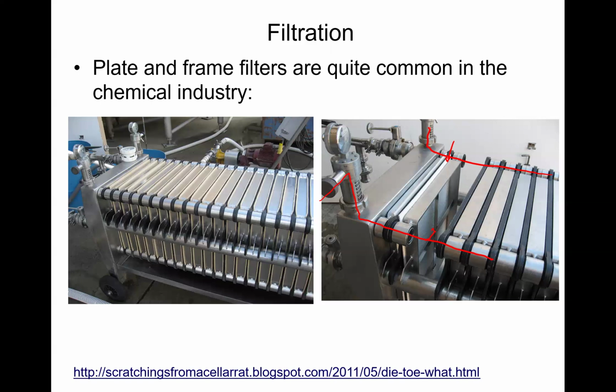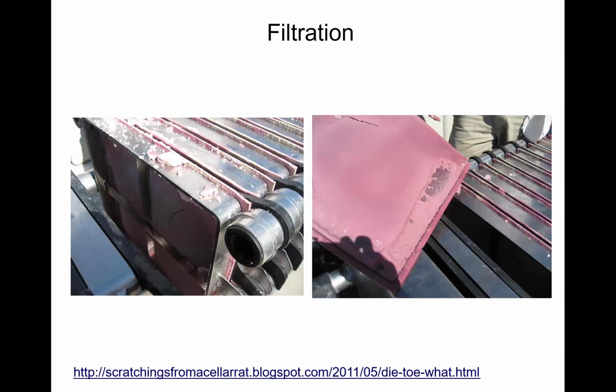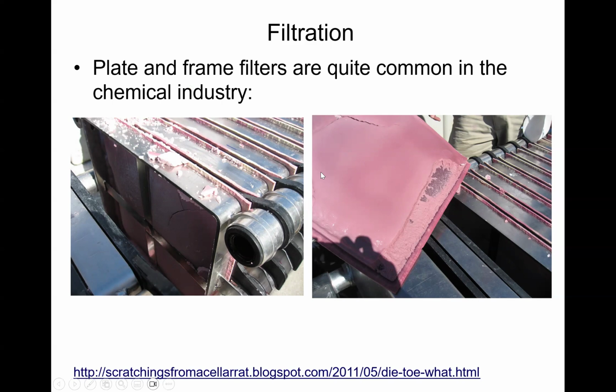In some cases in the chemical industry, that filter is collecting something that is the product itself. You can imagine something that precipitated in, say, the pharmaceutical industry, something that precipitates that is your active ingredient. And now you need to recollect it from the filter in order to use it. In some cases, and this is the case in this example, you're basically trying to remove solids from a liquid, and then that solid will be discarded. The solids that form are called the cake.